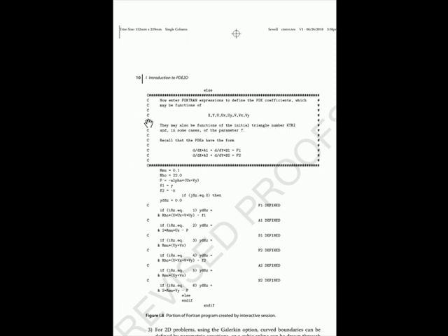And here's a portion of that Fortran program. It's all written for you automatically, just taking the answers that you gave either the GUI or the interactive driver and sticking them in the appropriate places. So it looks like a complicated program, but 99% or 95% of it is written automatically for you. For example, that interactive driver session, you input the F1, A1, so forth, and that ends up here. So either way, you end up with a Fortran program, and you run that using run PD2D, which compiles and links to the PD2D library and executes it.